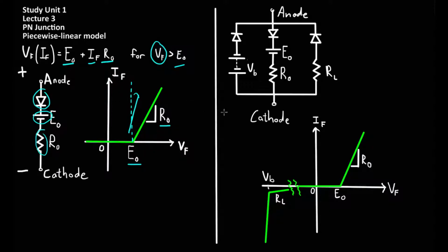For a model which more closely approximates the exponential function, the diode can be modeled to include the breakdown voltage as well as the slope of the current as it approaches breakdown. To do this, the idealized piecewise linear model is taken as the base model. It still contains R0, the turn-on voltage E0, but also includes two additional parallel branches, both consisting of ideal diodes, but reverse biased in relation to the main ideal diode.